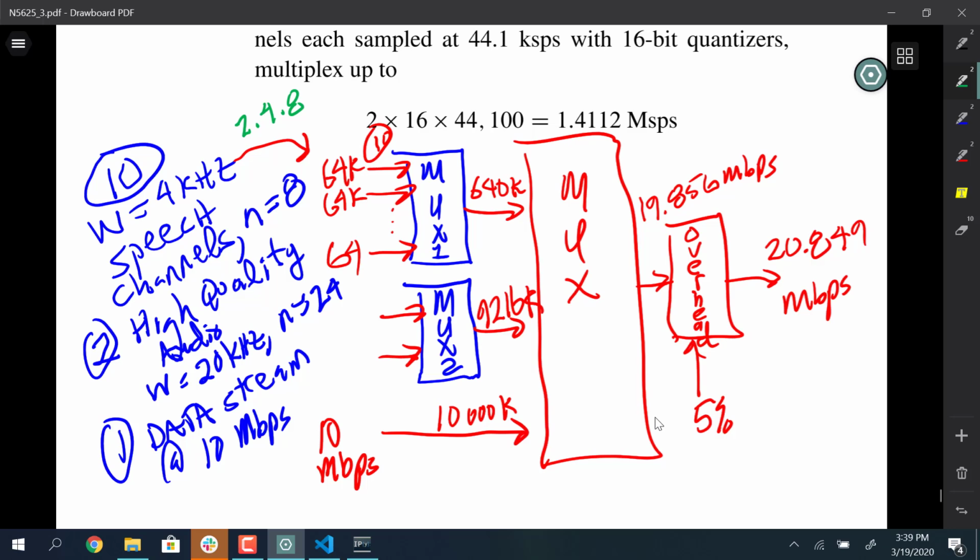It's pretty straightforward though. The only real signal processing comms analysis that has to be taken into account is Nyquist. If you're given a bandwidth, then you have to remember to double that bandwidth to handle sampling theory, and then just remember to multiply everything out. And you could specify an oversampling factor, like it's not good enough to sample at twice the highest frequency, you have to sample at 2.5 times the highest frequency, or 3 times, or some other scaling factor like that.